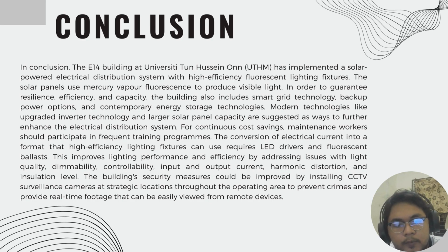This improve lighting performance and efficiency by addressing issues with light quality, dimmability, controllability, input and output current, harmonic distortion, and insulation level. The building security measure could be improved by installing CCTV,